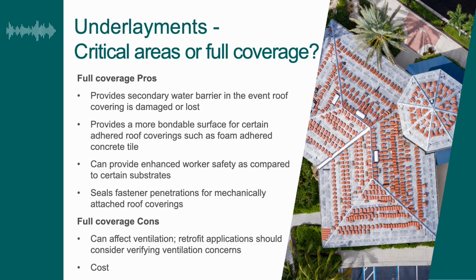We looked at the tile, the adhesive set tiles, and how great that fabric surface underlayment works with the tile application. And you can actually enhance worker safety. Why? Because a lot of underlayments have grippy surfaces, embossed patterns on them that facilitate the contractor's work on the roof so that they don't slip and fall. They can work more efficiently without having any safety concerns. And with mechanically attached roof coverings, if you have an underlayment with self-healing qualities, it's going to prolong the life of your roofing system.